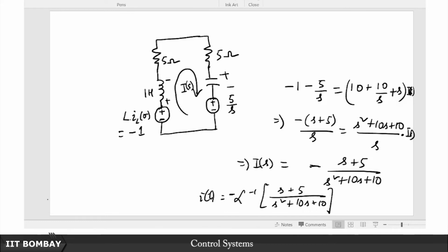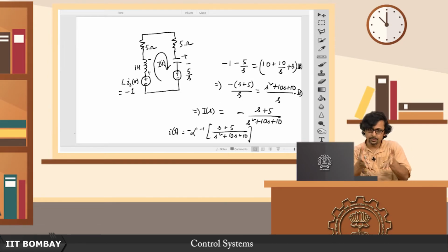So you see that not only does the Laplace transform help you in finding the transfer function or the zero state response, but it also helps you in solving for actual circuits when essentially you cut out the input and you see how the circuit comes to rest or decays, the variables decay, or the stable behavior of the circuit, right. So I hope that you see the versatility of this Laplace transform method that we just illustrated to you.